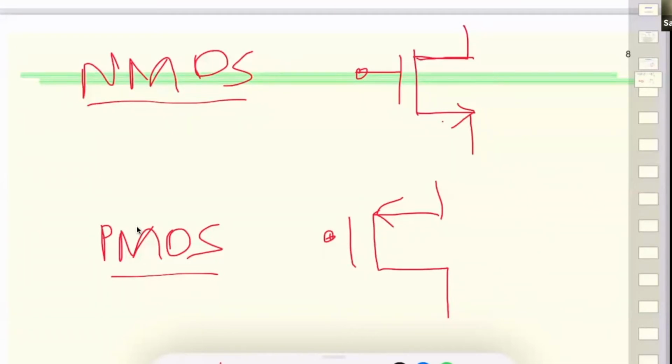But now we'll take the characteristics of NMOS and PMOS, and we will use that in whatever we do. For NMOS, we have to apply gate voltage to make it work, right? So we have to make the gate high to make it work. It has its drain and source resistance, which we knew for small signal, that was RDS.